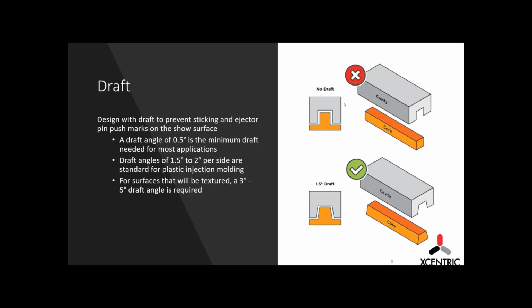At a minimum, with us at least, you want to have at least a half a degree of draft, and that will cover most applications. Ideally, you want 1 to 2 degrees. I say 1 to 1.5 to 2 there, but 1 to 2 will get you there.